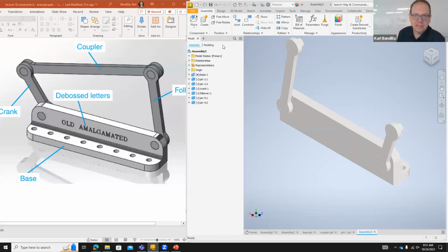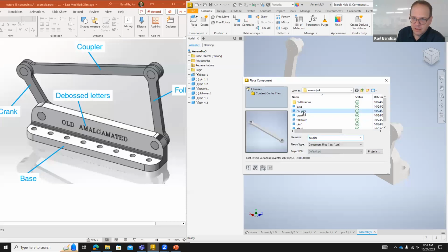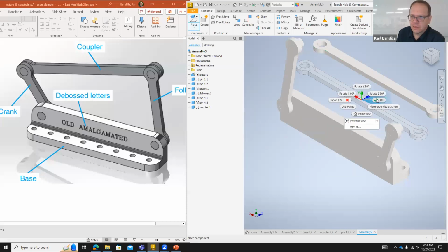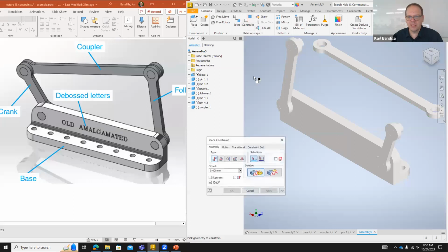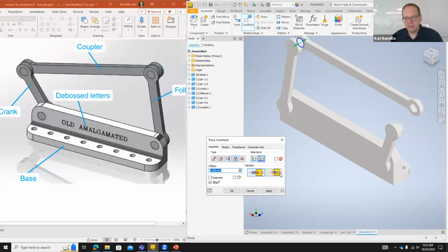So the only piece that we're missing is the coupler. Now you'll see when you do these kind of sets that are all together, and then they lock geometrically, sometimes it's good to have them come together in the way that you want it to look at the end. Because sometimes you would have the main part sticking down here, and then the other parts can't move, and so sometimes you have to play around with it a little bit. Constraint, another insert, that one, and then of course the same at the other end.